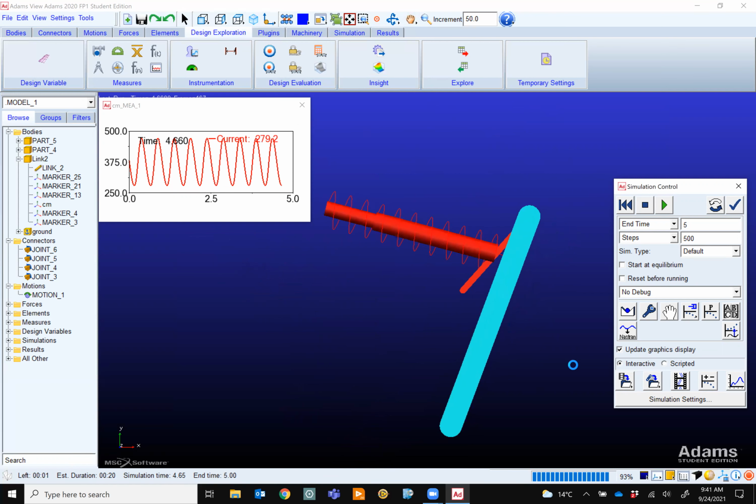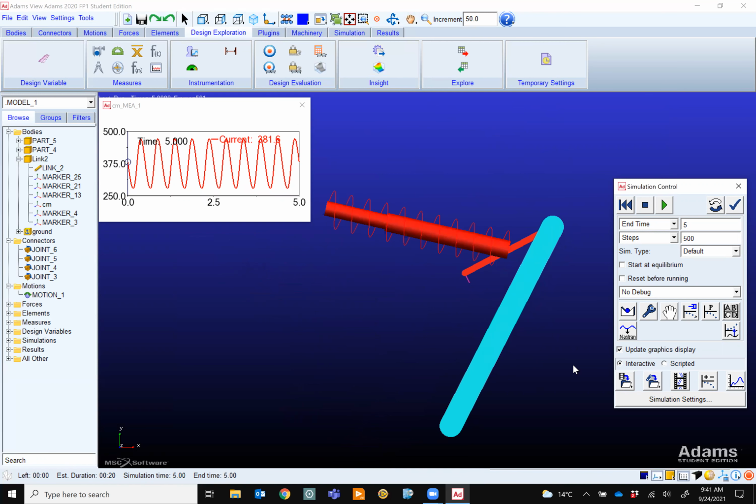Besides being super nice, it also sometimes gives us some good information while we are running the program to stop it. And it's not limited to just the measurement of the displacement. Again, if I go to design exploration, this caliper gives me a bunch of data. But let's say for some weird reason, Minchi is interested in measuring the distance between this point and this center of mass. Then you can create your own measurement. You click on this one. You see, create a new point-to-point measurement.